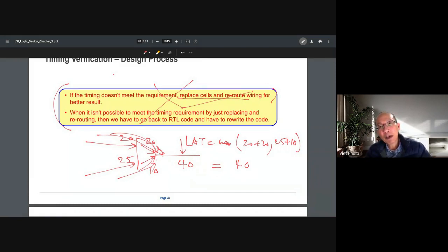They just run in parallel for maybe 20, 30, even up to 100 micron, and that causes crosstalk. However, those crosstalks are not enough to cause real trouble, just mild trouble. When they have it, they will try to reroute the signal, so they won't be in parallel anymore.